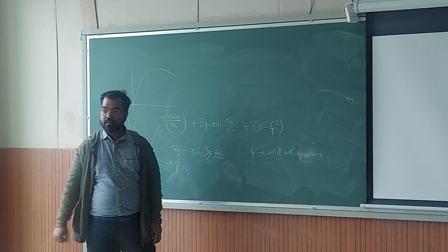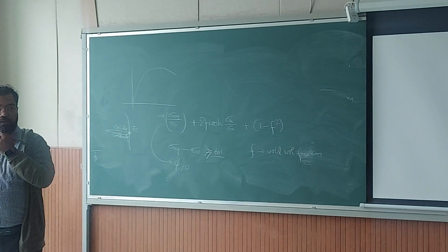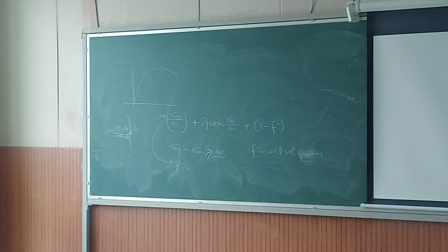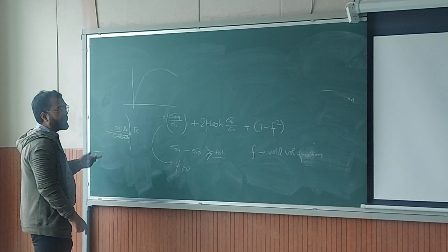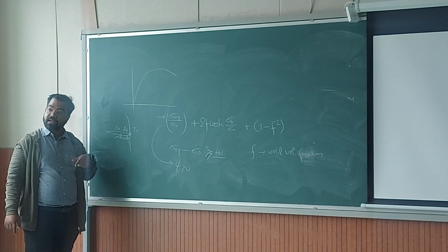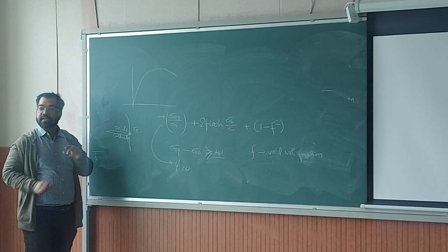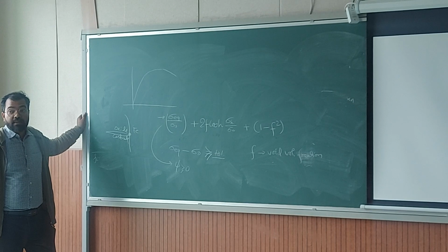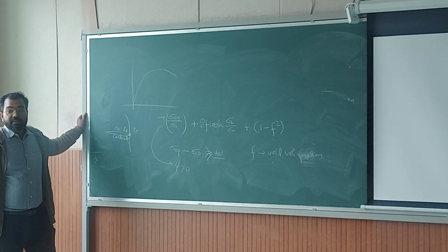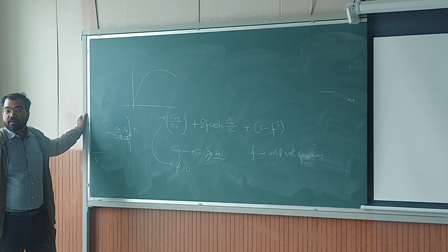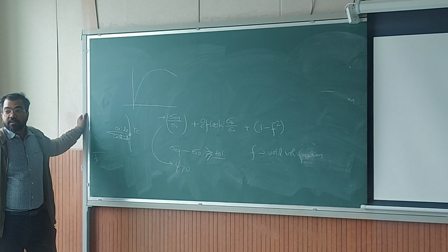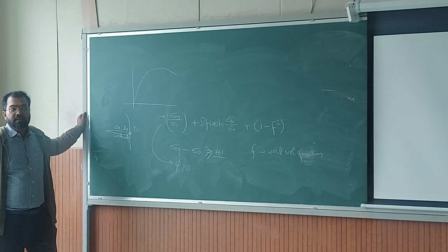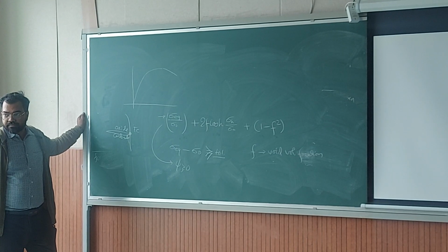Okay. So then you know that this is very specific to ductile damage. Whereas the previous one, where you had omega, can also be used for brittle fracture. That is very generic in nature, so that formulation you can use for a combination of ductile and brittle fracture. Because there you just need to change the kinetics from where omega is equal to 0 to omega is equal to F. What path that follows will describe your ductile behavior or brittle behavior.